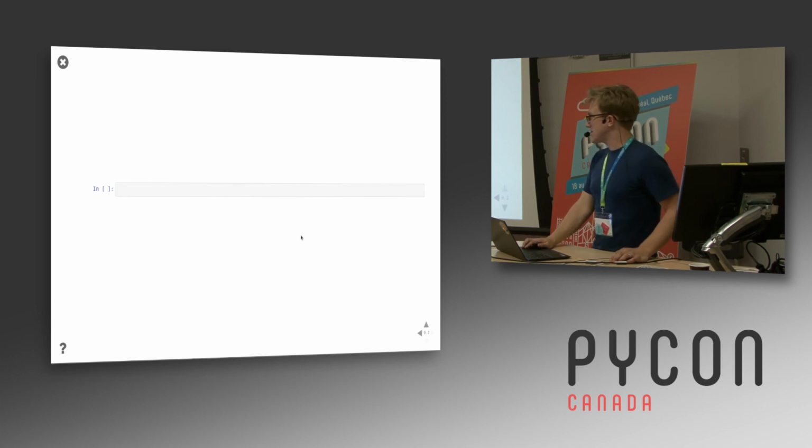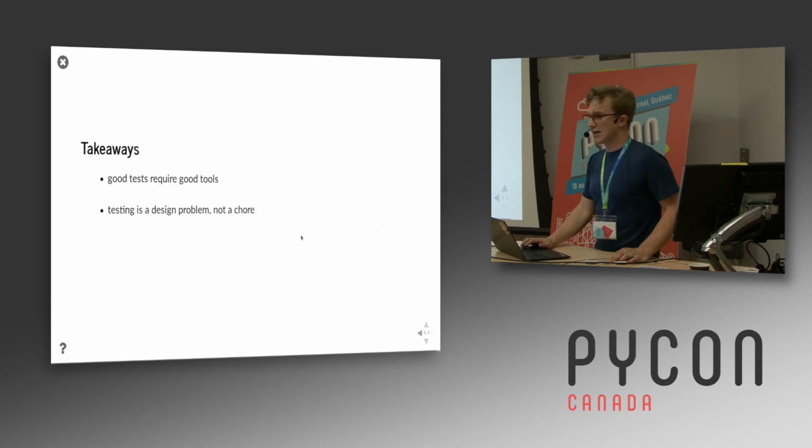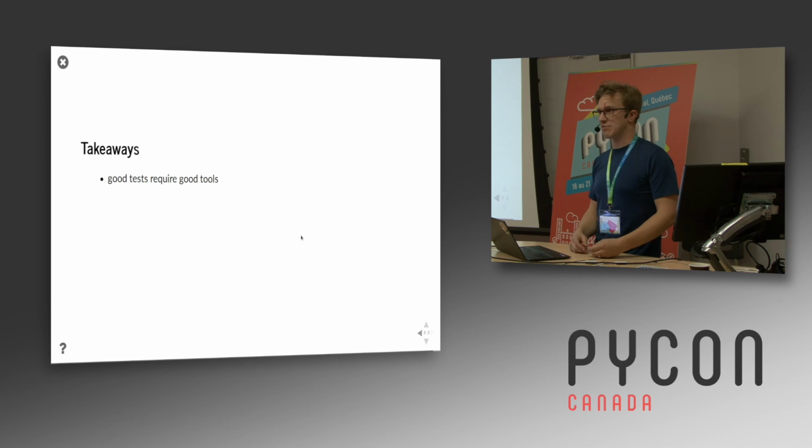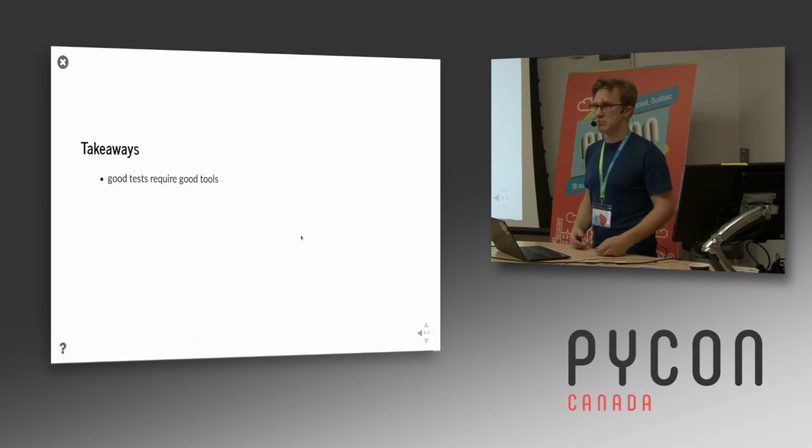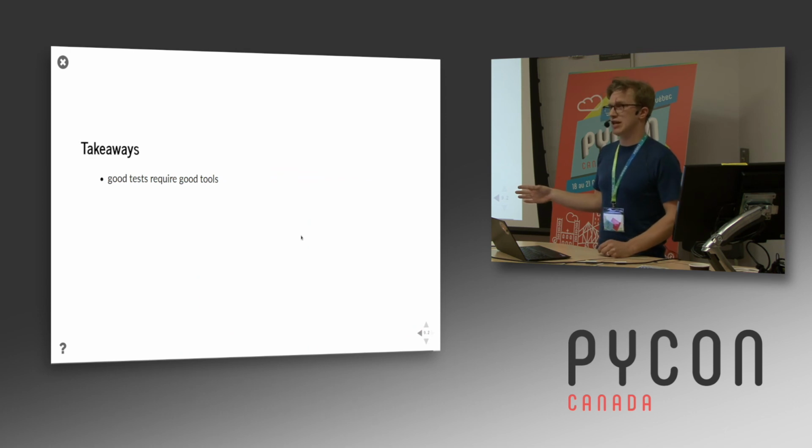Yeah, so we're not using MATLAB, but we are using a similar tool called GAMS, which is the General Algebraic Modeling System. It's just a language for doing algebra problems. So we're writing minimization programming in that language, and then we can take these networks that I've been drawing, and there's one or two things you have to do to make them easy for that to consume, but then you can put them into that package, and you can run power flow, and you can do optimization problems.